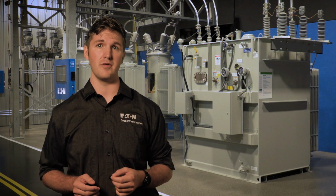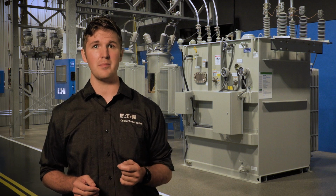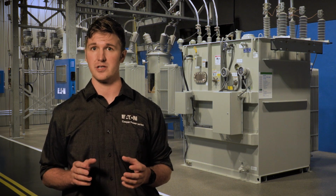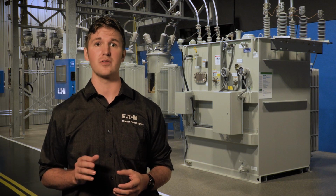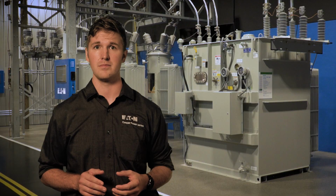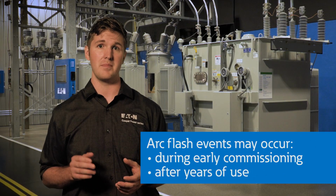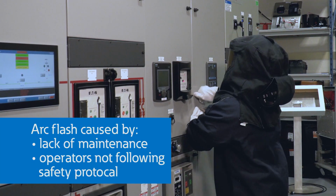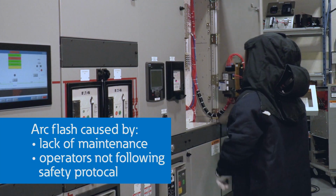Medium voltage distribution transformers deliver a significant amount of power from the grid connection to the secondary with high amps on the low voltage side. This extreme amount of power is throttled only by the electrical impedance of the transformer during a fault condition. However, it is still more than enough to devastate equipment or personnel if an arc flash event were to occur. Arc flash events may occur during early commissioning or after years of use, but are often due to lack of maintenance or operators not following safety protocol.